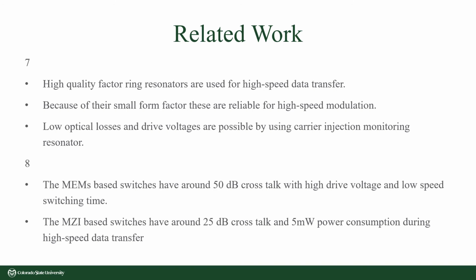Next paper is an analysis of crosstalk in optical switches. The authors conducted a few experiments and found the following results. The MEMS-based switches have around 50 dB crosstalk with high drive voltage and low speed switching time. The MZI-based switches have around 25 dB crosstalk and 5 mW power consumption during high-speed data transfer. Ring resonator-based switches have low crosstalk and low power consumption because of their small form factor.